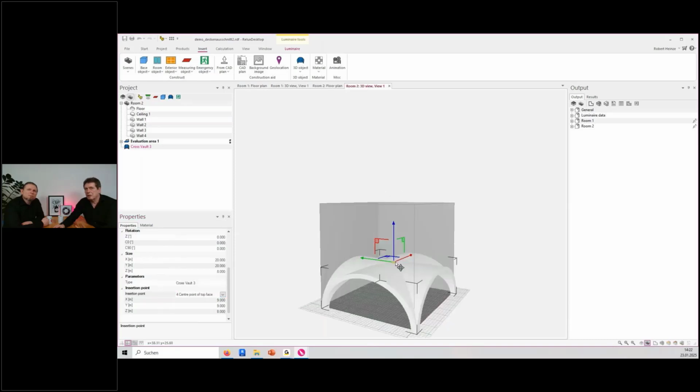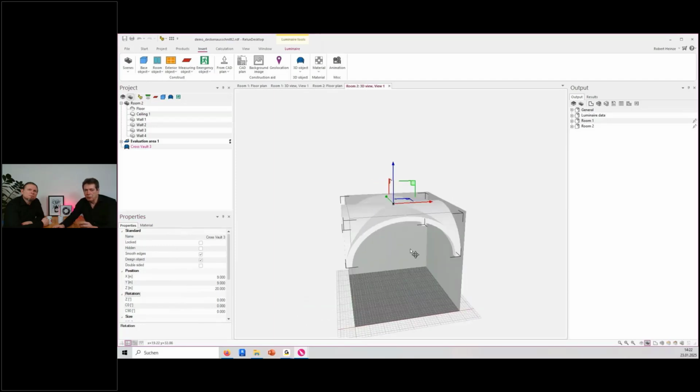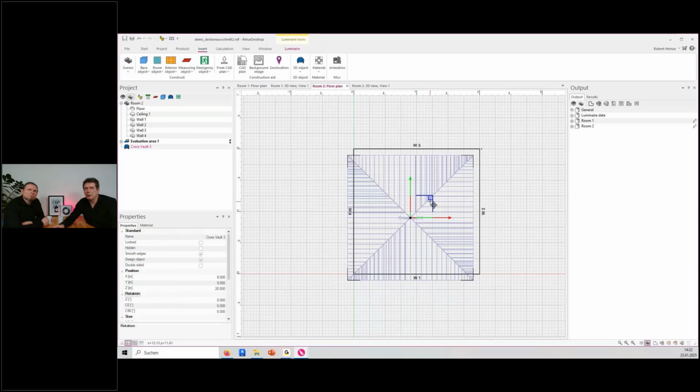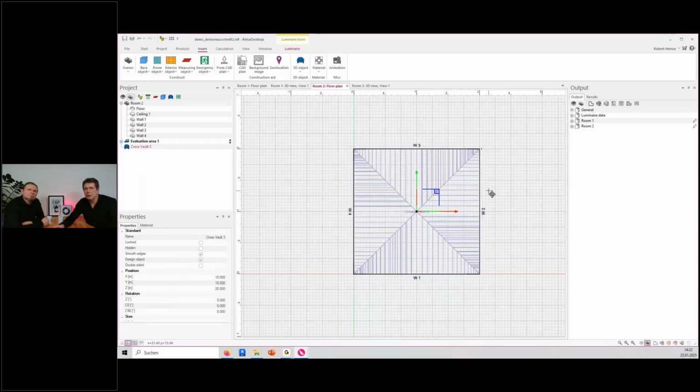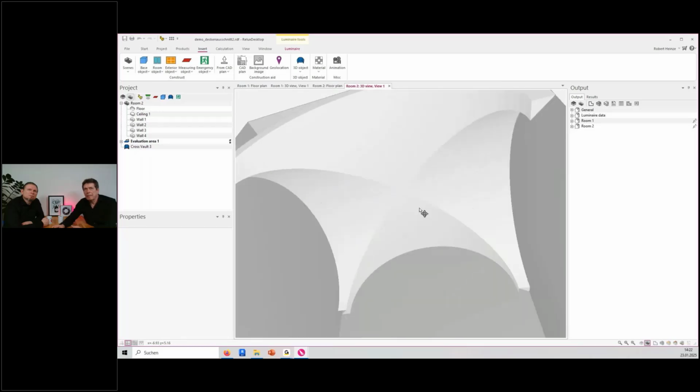Now the insert point is up at the upper part of this object, and now I can very simply set the height to the room height, and now it is exactly on top of the room, and here a little bit to center it in the room, and then we will have a really good ceiling object in our project.